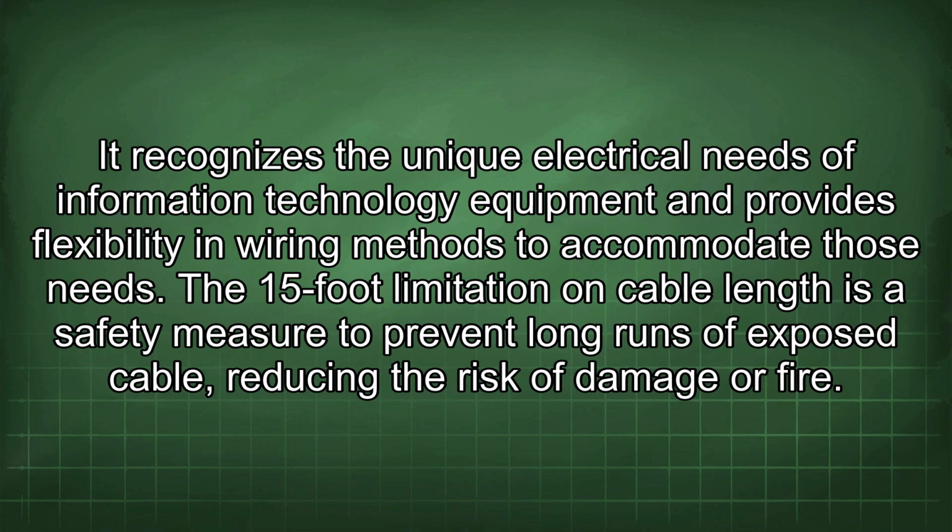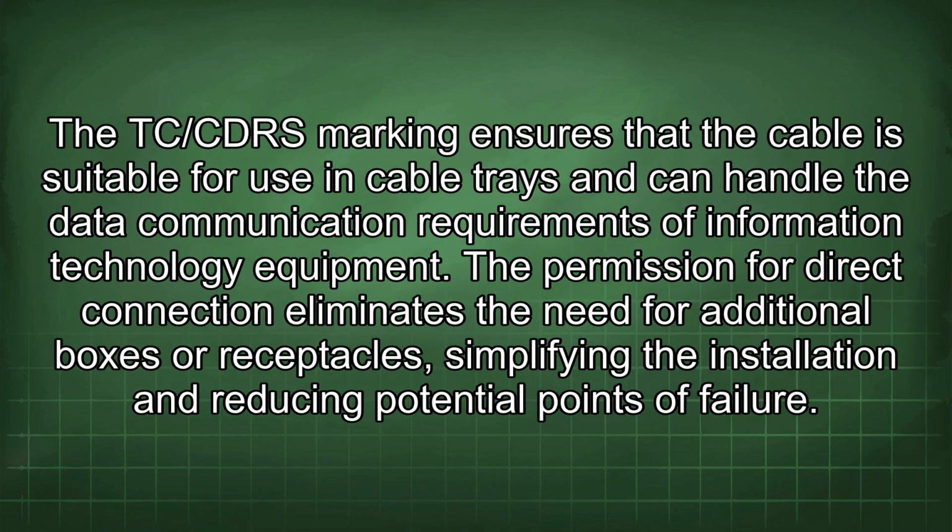The 15-foot limitation on cable length is a safety measure to prevent long runs of exposed cable, reducing the risk of damage or fire. The TC/CDRS marking ensures that the cable is suitable for use in cable trays and can handle the data communication requirements of information technology equipment. The permission for direct connection eliminates the need for additional boxes or receptacles, simplifying the installation and reducing potential points of failure.